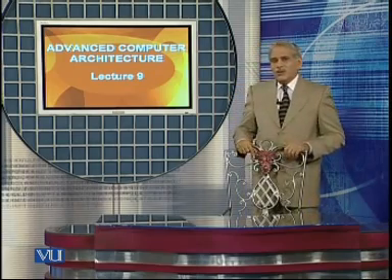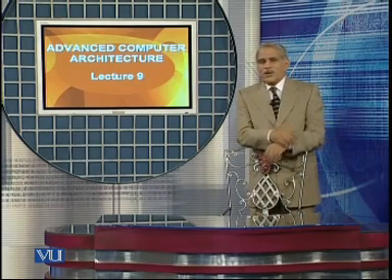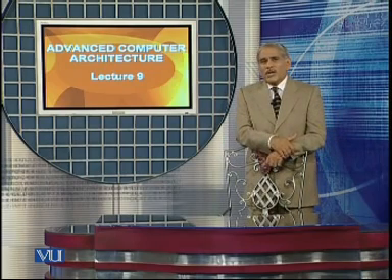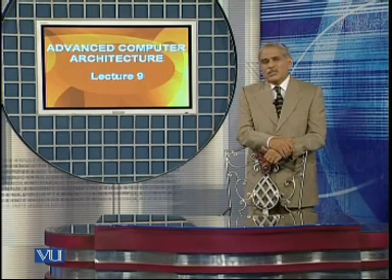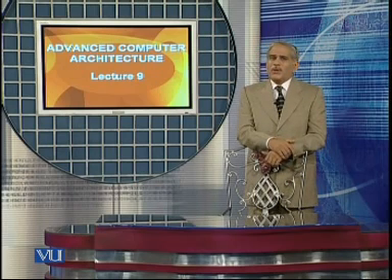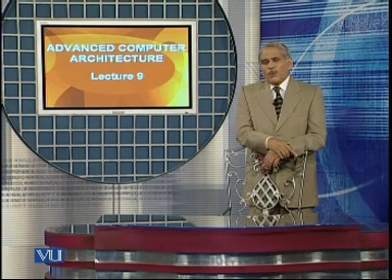So this means that now we need a clock where the time period of the clock is 1 microsecond as compared to the clock required for single cycle data path, which we assumed to be equal to 5 microseconds. So considering this, we can now see that we can perform different operations in different clock cycles.